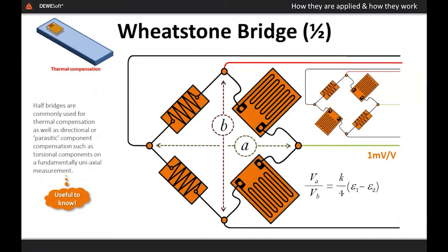It is a method of gauge application that can actually have multiple purposes. For example, the gauges could be placed in the same direction and effectively double the output, depending on where in the bridge you place them, since it is possible to effectively subtract the load from each other if you aren't careful about bridge locations.